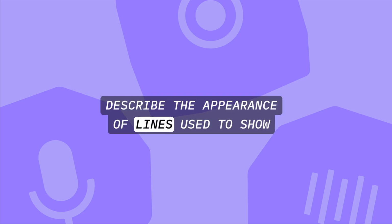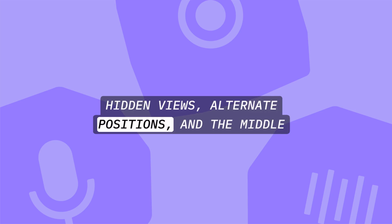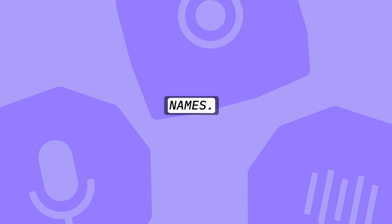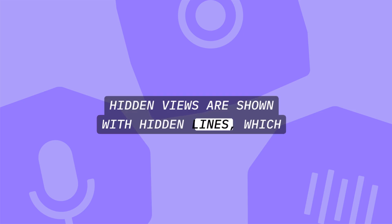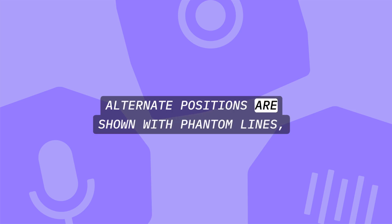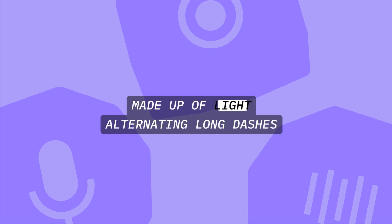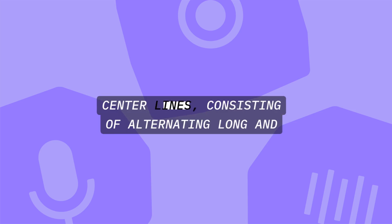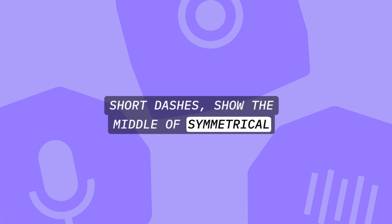Describe the appearance of lines used to show hidden views, alternate positions, and the middle of symmetrical objects, and give their proper names. Hidden views are shown with hidden lines, which are short, evenly spaced dashes. Alternate positions are shown with phantom lines, made up of light alternating long dashes and two short dashes. Center lines, consisting of alternating long and short dashes, show the middle of symmetrical objects.